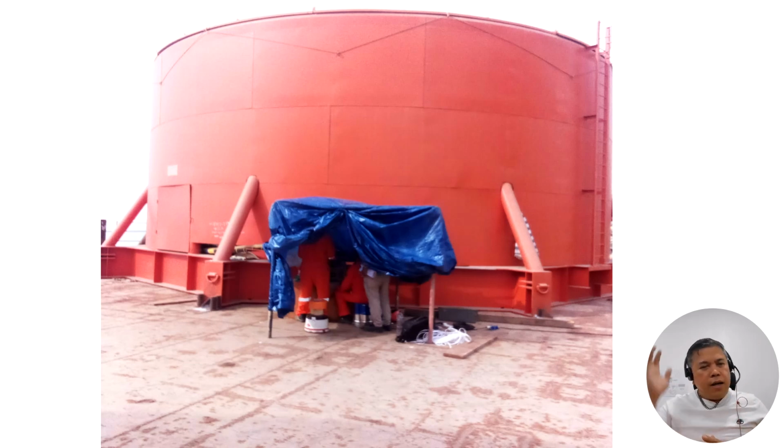From the J-tube we'll go straight to the J-tube, and then we will install it in the platform on the deck, and then we have a power JB, and then we will terminate and splice those cables in that particular portion, and then we will run towards our controls, supply, etc.